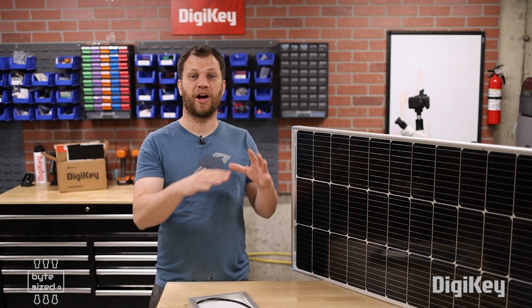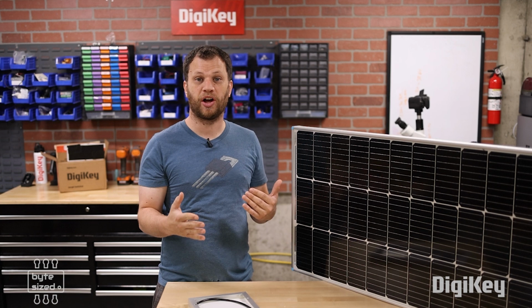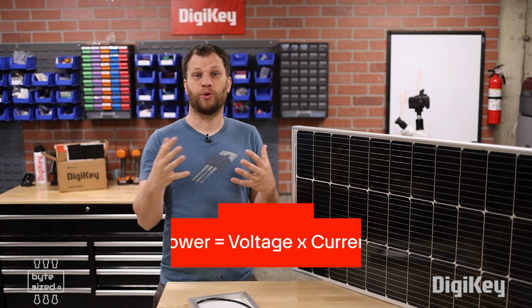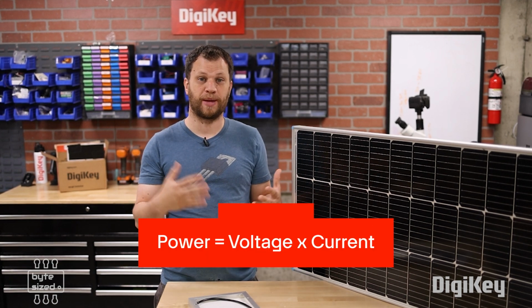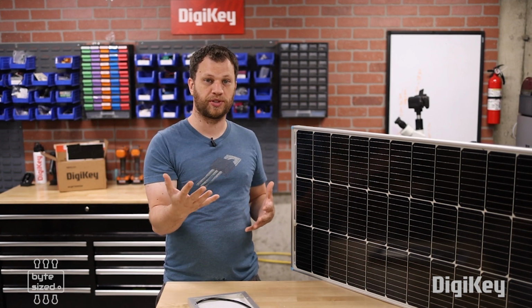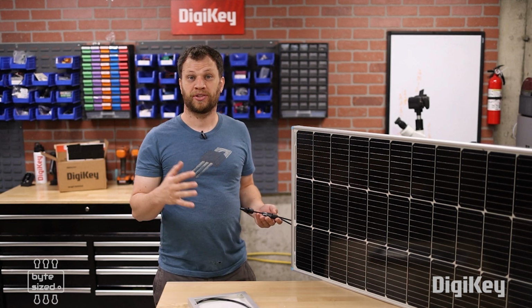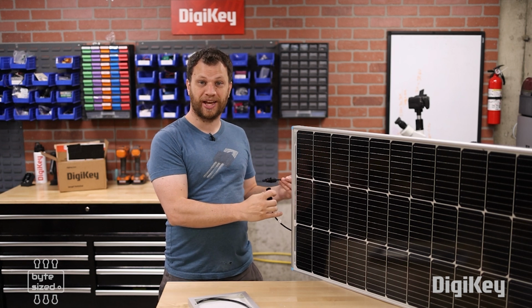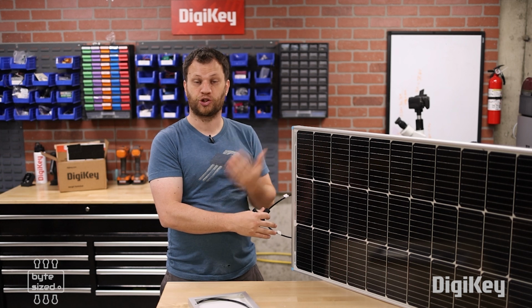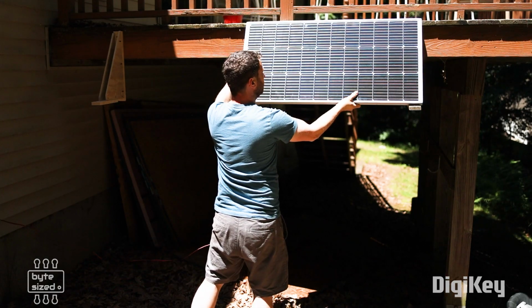Solar panels operate on a power curve. That is to say, the amount of power that they can produce is dependent on the amount of load attached to them. And if you remember, power is equal to voltage times current. So when there's no load attached to it, the voltage is at 24.3 volts and the current is at 0, therefore the power it's producing is 0. Similarly, if I attach these two connectors together and put an infinite load on the panel, the current goes up, but the voltage drops to 0, and therefore the power it's producing is also 0. To get power from a solar panel, we want to be operating somewhere in the middle of that curve.